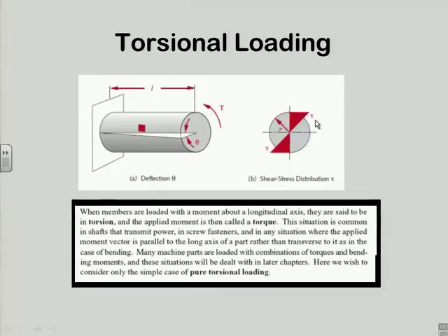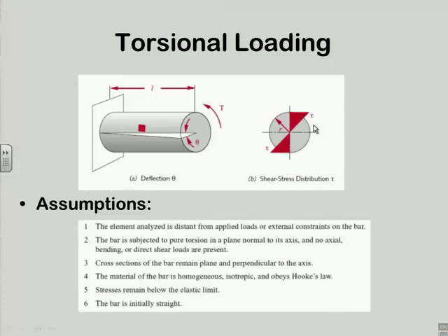It's shear on vertical planes, and thus this is not plus and minus. That's just shear. And I have the maximum amount at the outer fiber and 0 at the center, and it's all the way around. I show it like it's the top and bottom. It's all the way around. Okay? So the whole outer fiber is getting sheared maximally, and the axis is getting nothing.